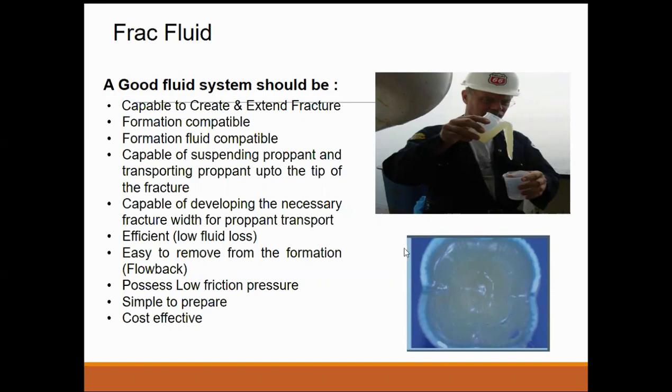For some reason, it might react with the rocks and formation fluid and create a solid substance which can choke the perforations, and it may not allow you to pump a frac job because perforations are the only entry point for the frac fluid to enter. So if they are choked, you won't be able to pump.